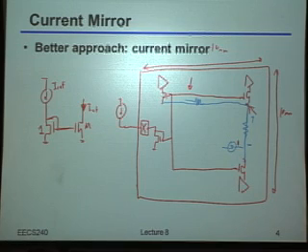Because remember, all voltages are relative. There's no such thing as one wire that gives you a voltage. There's always 2 points you have to take to create a voltage. Okay? And for transistors in particular, at least for this biasing, it's the VGS you care about, right? So this is really particularly bad because even if this ground here had no current flowing through it, the VGS you created was relative to ground only at this point on the chip, right? If you shipped that same quote-unquote voltage, or really that same one wire, to some other point on the chip, the ground may not be the same, okay? And so because of that, the actual current you get could be very different.